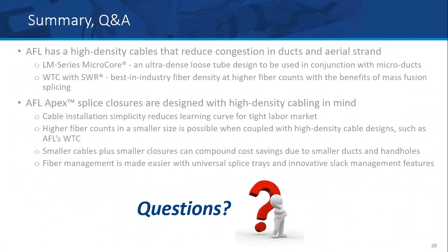It says, so if I wanted to ribbonize the LM200 series, could I still mass splice it to a ribbon 250 micron fiber? Yeah, so there's a couple different features, and I'd encourage you to either talk to your sales rep or check out our fusion splicing section on the website, aflglobal.com. I don't want to speak out of turn, but we've got a new ribbonizing tool that I believe can ribbonize 200 micron fiber into a 250 micron pitch.